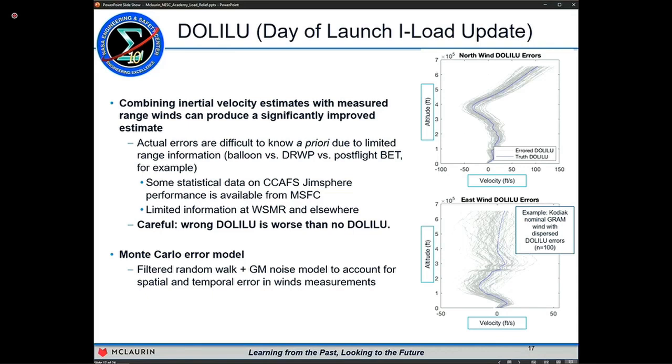What we find is that we can tune the inner loop separately, so the inner loop stability margins aren't affected by the outer loop closure. The inner loop autopilot stays very simple. It's just a PD or PID control law with bending filters, and then we can reduce the effective acceleration feedback gain. So all these things point towards more tunability, better performance, and better stability.